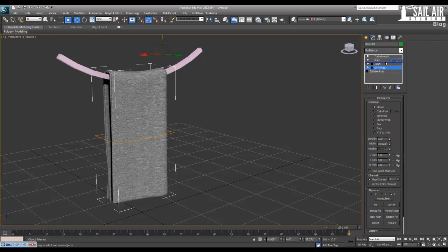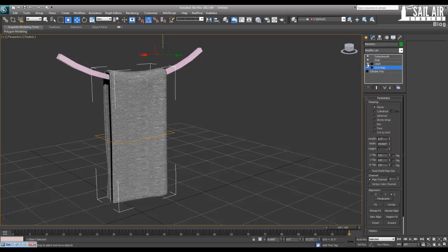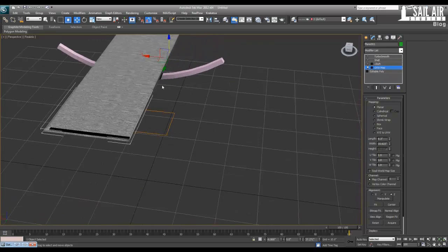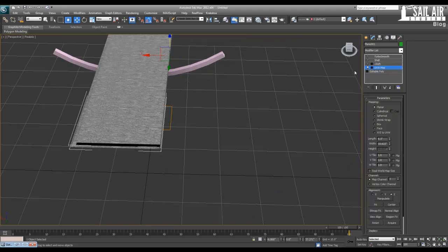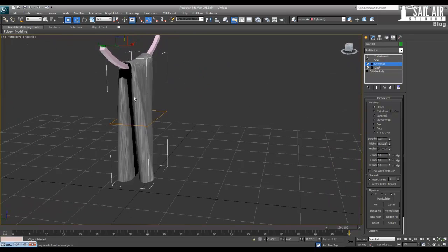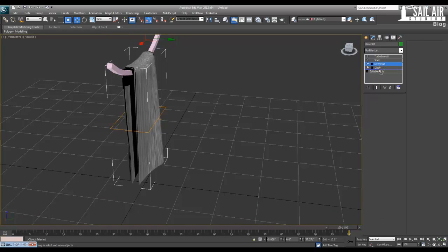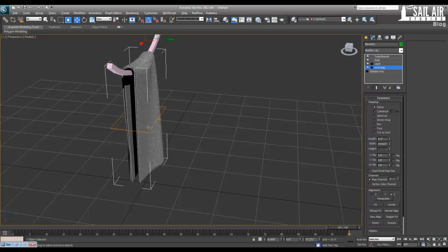As you can see, above the cloth, below the cloth. Make sure it's below the cloth. This is because it makes a UV map of this plane right here. If you put it above the cloth, it makes a UV map of this kind of looking material, which looks really wrong, and it's not all flat and perfect. So we want to make sure that the UV is added before the cloth.